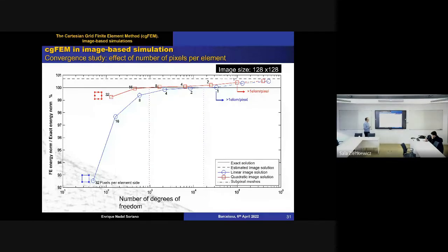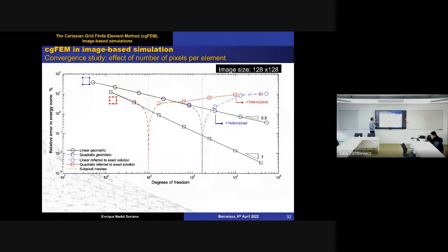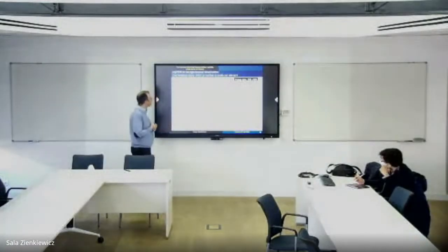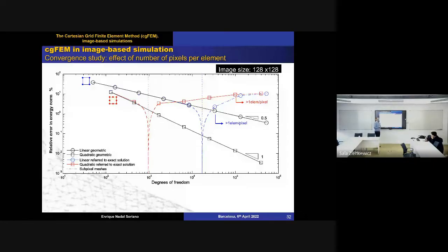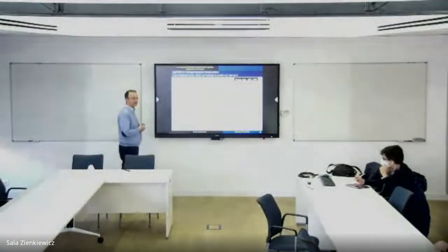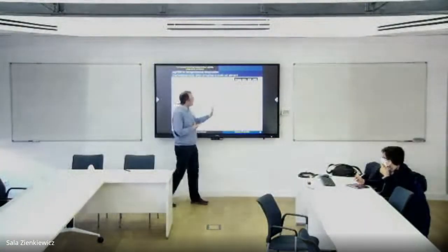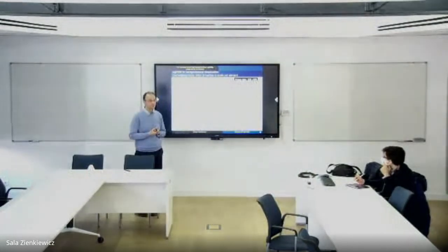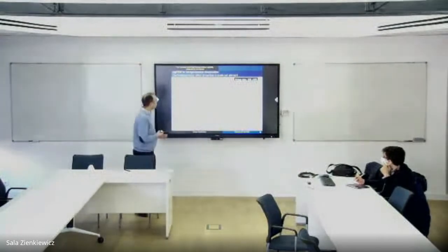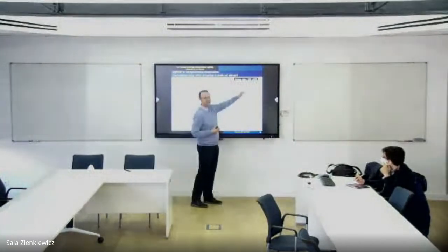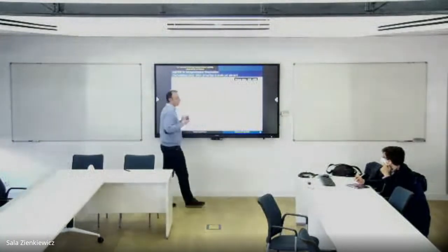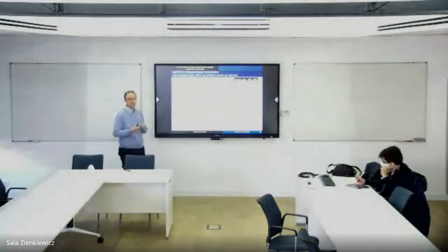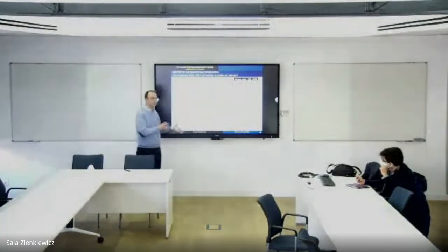Regarding the convergence, we observe exactly that. At the beginning, on the left-hand side of the picture, with many voxels in the element, we have more or less the right convergence rate according to linear or quadratic elements. But when we make finer and finer meshes preserving the pixelization, that is, the geometry definition, we stop the convergence rate because we are solving a problem which is not a cylinder under internal pressure, but the pixelization of the cylinder.